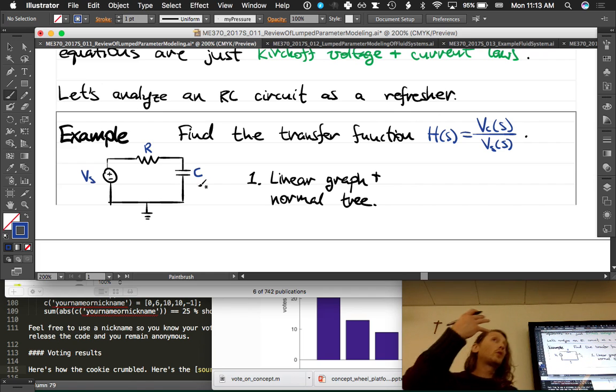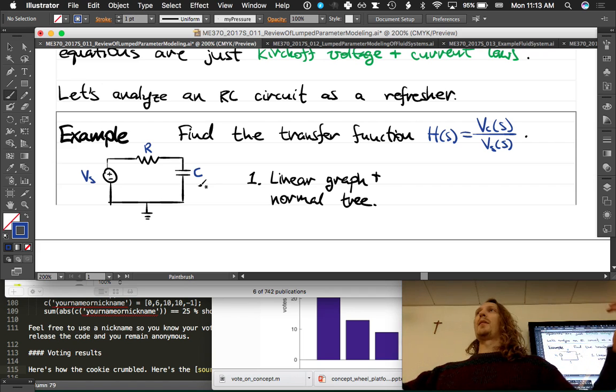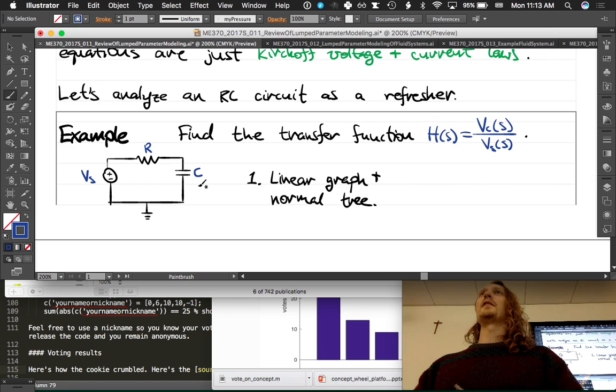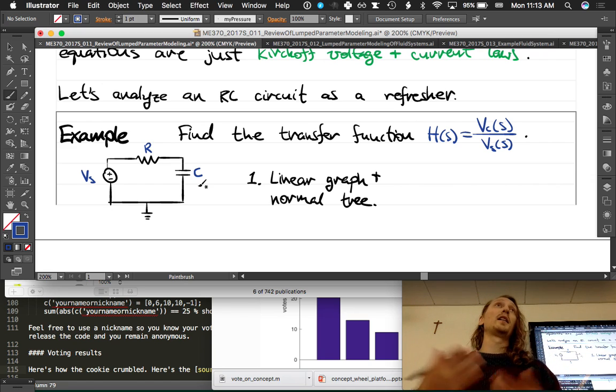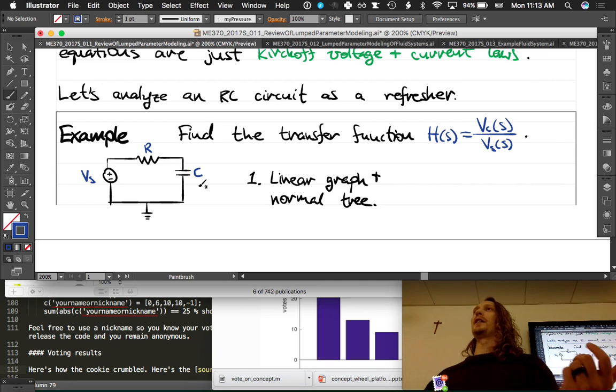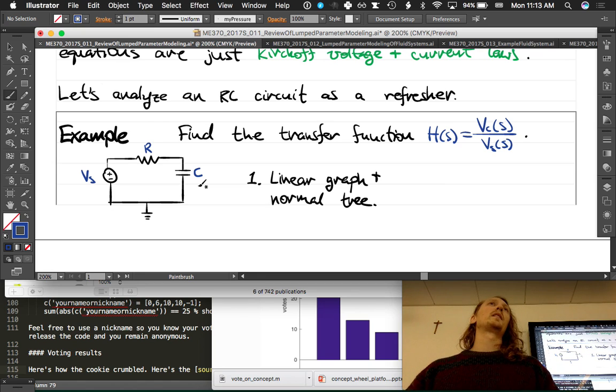And we are going to use the technique that we're going to develop the whole state space model and then use that last result that we found last week to apply to this problem to find the matrix transfer operator and the matrix transfer function. However, this is a single input, single output system, isn't it? And so what is the dimensionality of the matrix transfer function?